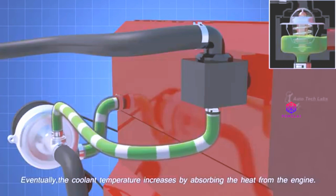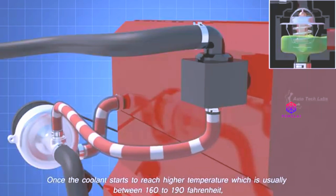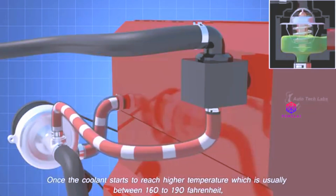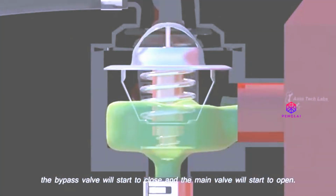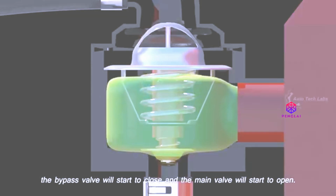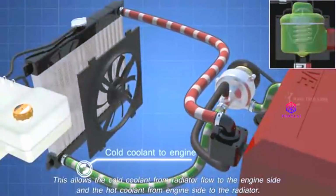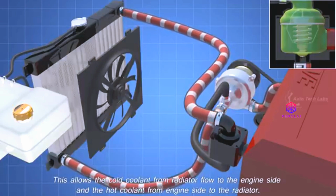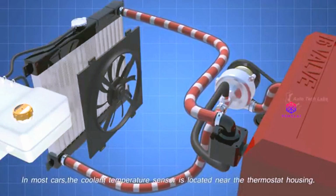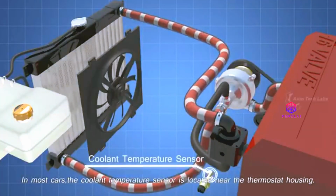Eventually, the coolant temperature increases by absorbing the heat from the engine. Once the coolant starts to reach higher temperature, which is usually between 160 to 190 Fahrenheit, the bypass valve will start to close, and the main valve will start to open. This allows the cold coolant from radiator flow to the engine side, and the hot coolant from engine side flow to the radiator. In most cars, the coolant temperature sensor is located near the thermostat housing.